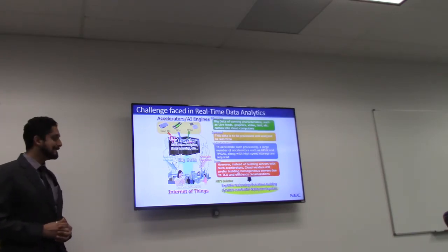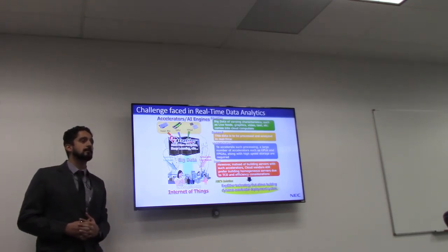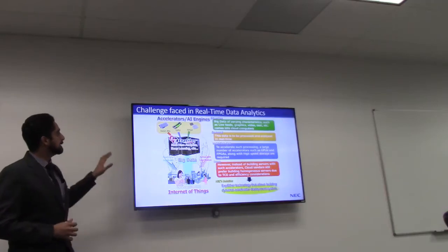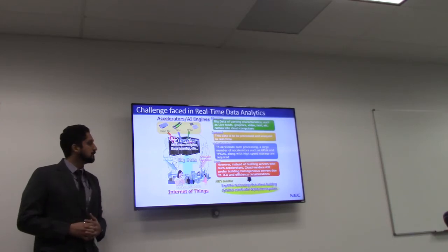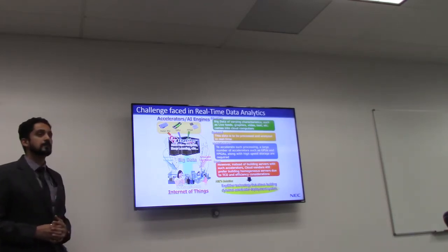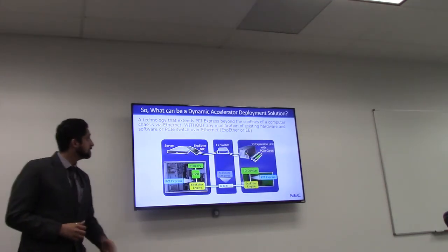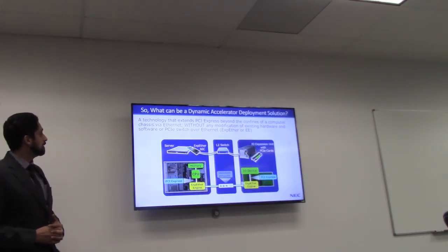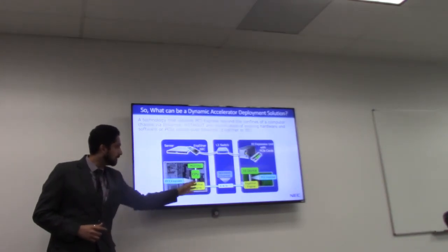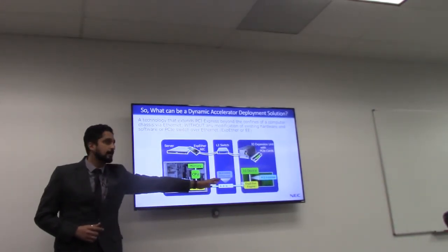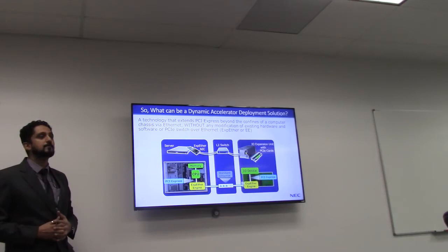With Express Ether, we are introducing a system-on-network principle, with which we can interconnect all these computing elements as well as the sensor elements to the CPU without the involvement of any new software stack. With that, I would like to introduce Express Ether, which is a PCI extension over Ethernet. In this technology, we take the PCIe slots out of the chassis of the computer and extend them over Ethernet, making sure that we do not have any performance lag.